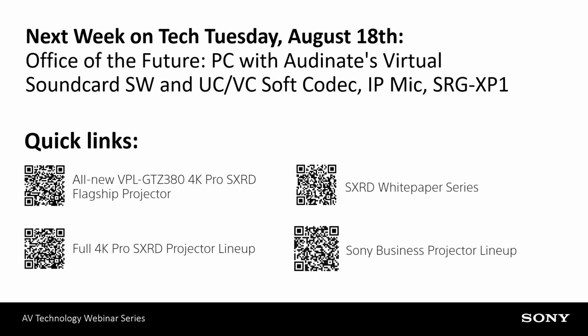Terrence asks, how do you see projection image quality standards evolving over the next 3 to 5 years? The biggest changes probably will be the continual development of the light source. From a projector point of view, the image, the brightness, and the amount of color gamut it can reproduce, or the amount of color range, is directly proportional to whatever light source you're using.